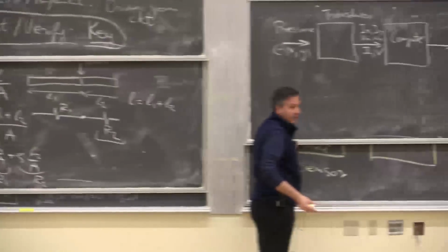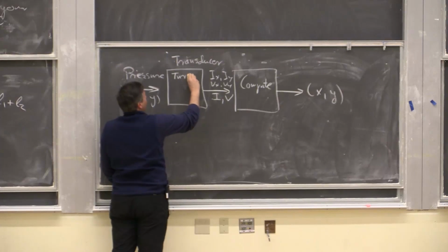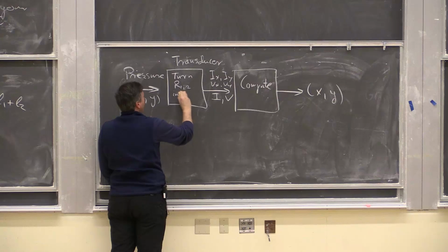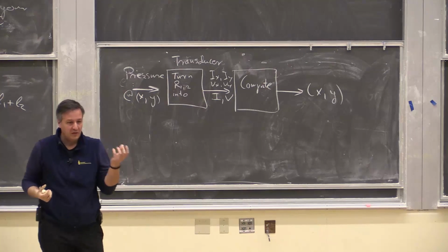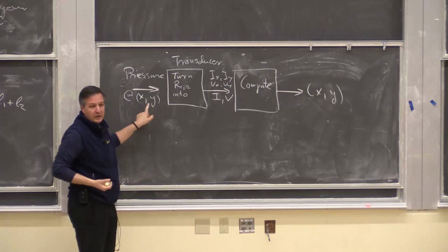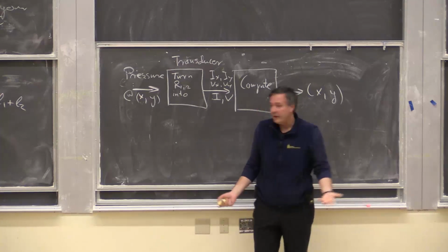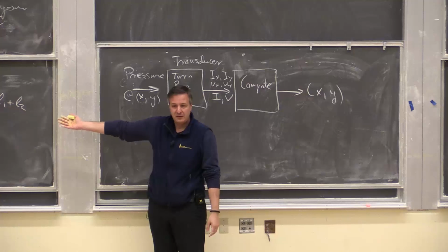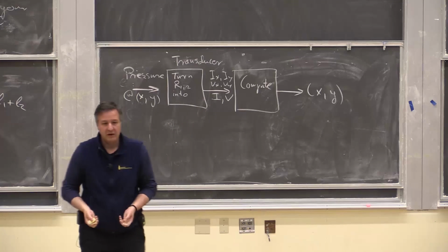Right? So in this resistive touch screen, I would turn R1, R2 into current or voltage. I want to turn these values into current or voltage because these values of R1, R2 give me the coordinates. Right? Okay. What other element do I need to do that? I only have resistances, right? What else do I need to be able to generate or have currents and voltages in the circuit?